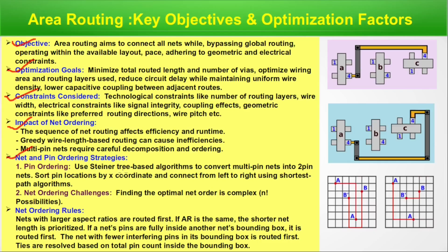Pin ordering: use a Steiner tree based algorithm to convert multi-pin nets into two-pin nets, sort pin locations by x coordinate, and connect from left to right using a shortest path algorithm.